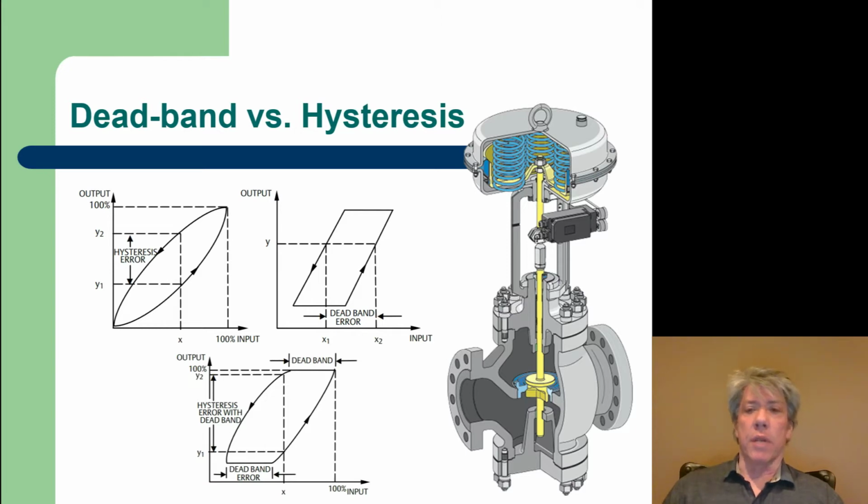And of course this is a process control valve. There's even a little dark gray or black box there that's probably supposed to be some type of positioner. If you notice, the stem goes down into the body of the valve, and so that stem has to be sealed because you've got some type of fluid flowing in the valve, whether it's a gas or a liquid, whatever the case may be. There's always something called packing that's required around the stem, and that packing seals the motion of the stem so that the fluid doesn't leak out of the control valve as the stem moves. So the problem, of course, is that there's a lot of friction between the stem and the packing.